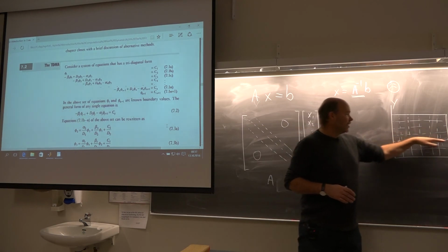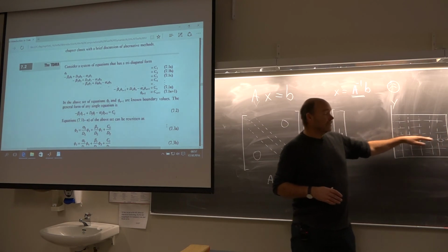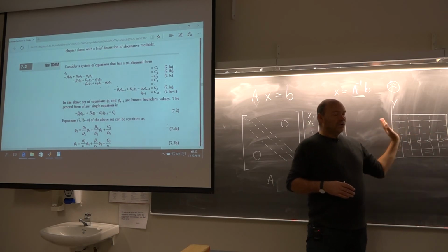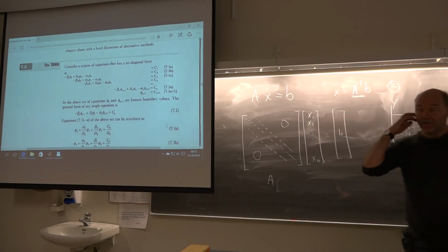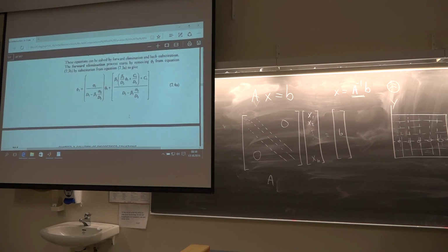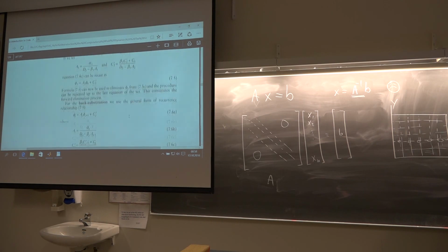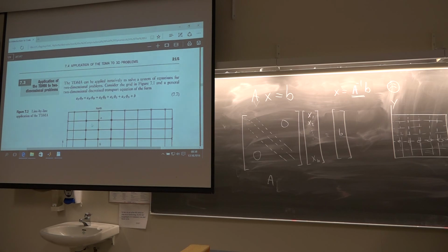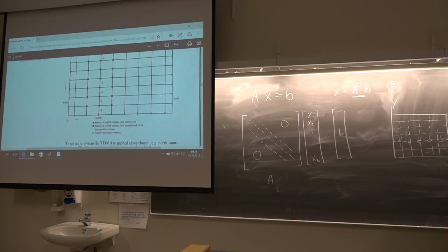The information can travel quite fast along these lines when you solve it like that, but you should use every other line as well and think in both directions. So yes, with TDMA it's possible to set up an iterative solution algorithm, and that is not so tricky and fairly easy.